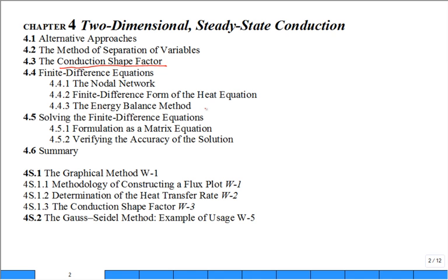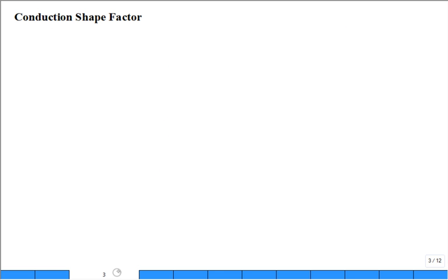And then I'm going to talk about an energy balance to solve for a two-dimensional steady state temperature field. It's conduction in a two-dimensional domain. It's really a finite difference technique that we're going to employ. What we get is that one differential equation valid throughout the whole domain is replaced by a bunch of algebraic equations, expressed as energy conservation at unique locations in the domain. So let's go ahead and jump into it.